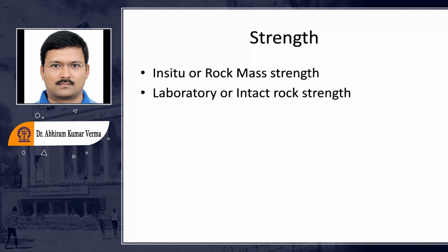Whereas in the case of rock mass, we need a large setup of equipment for the strength determination, and the preparation cost and the labor cost will be too much. So that's why we are preferring these laboratory properties over the rock mass properties, and possibly a few rock mass property determinations.